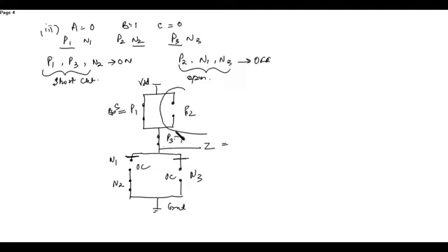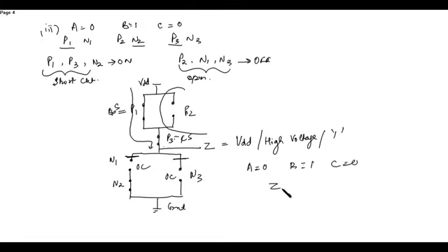This is closed circuited, this is closed circuited. So the output obtained will be VDD through this path. VDD, or you can say this is the high voltage, or you can say it as 1. So when A is equal to 0, B is equal to 1 and C is equal to 0, the obtained output is 1. So this is also now satisfied, the third condition.